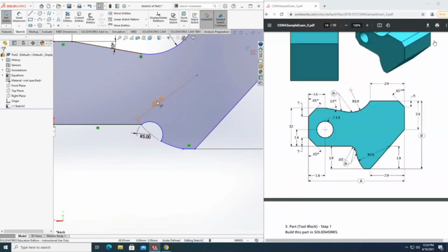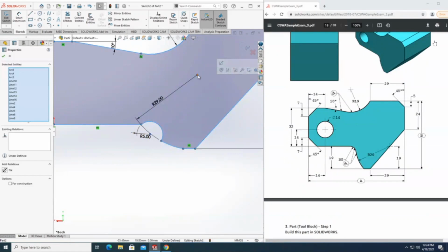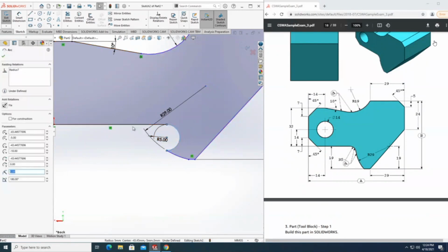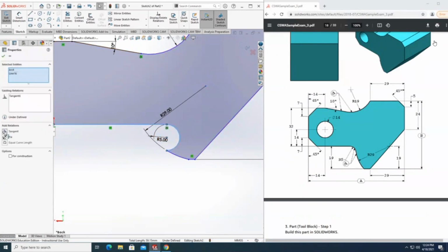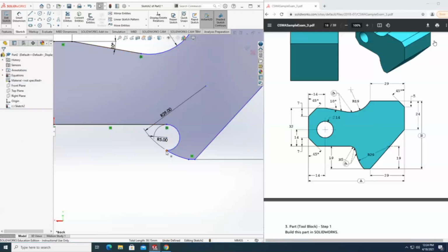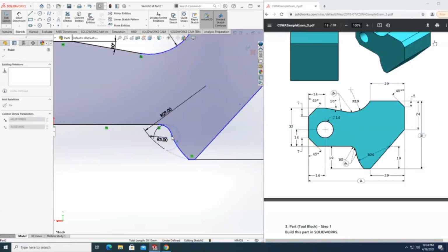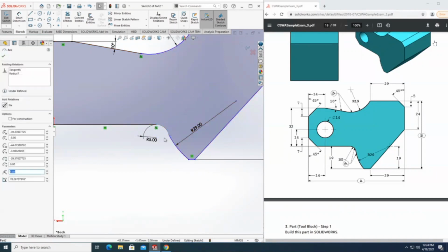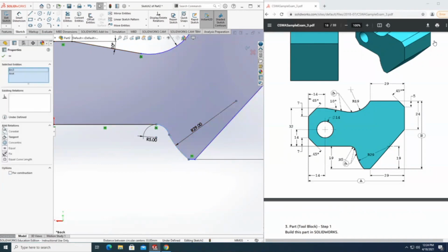We can look at this situation over here, and we can still move a lot of parts, and we need to start basically defining or giving the dimensions and relations. So what we'll do here is we'll start with giving this line and this line being tangent, and now they're tangent. And then I'm gonna move this arc to somewhat how it's gonna look, this is kind of what it's gonna look like. So that's good. Now I'm gonna make this arc and this arc both tangent, because this is what this symbol is telling us, that this arc and this arc are tangent. So I'll do that.